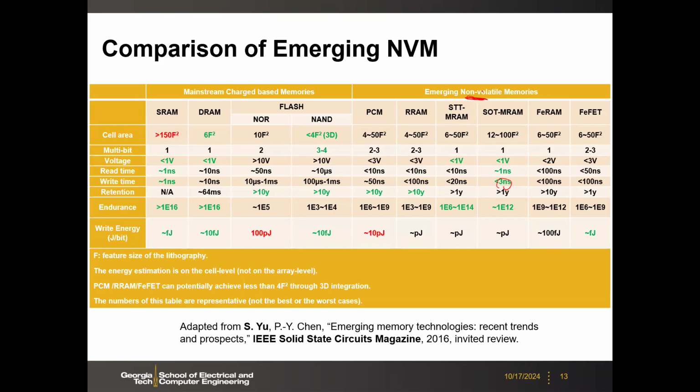And then the endurance, okay. Endurance has a wide range for those emerging memories, typically no higher than 1E12, okay. And in many cases, only like 1E6, okay. So this is a little bit better than the NAND flash, because NAND flash, as I told you before, nowadays only has 1000 cycles, 1E3 cycles.